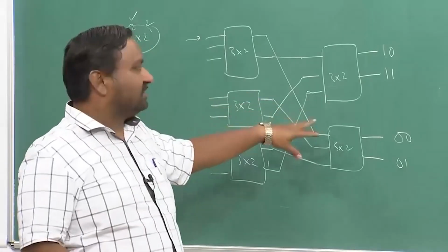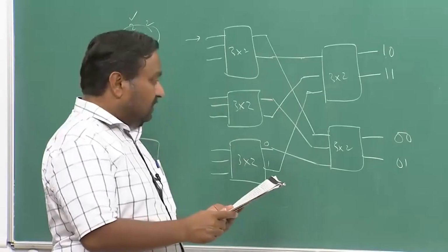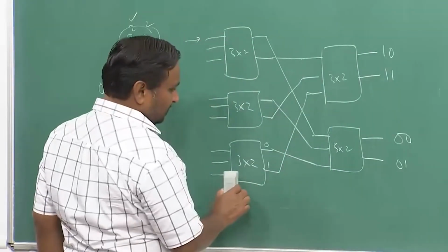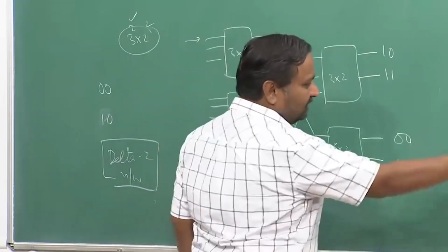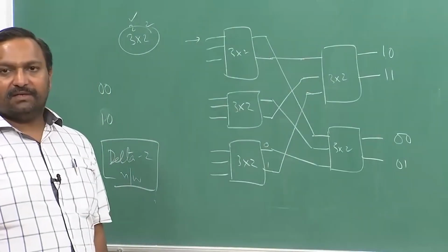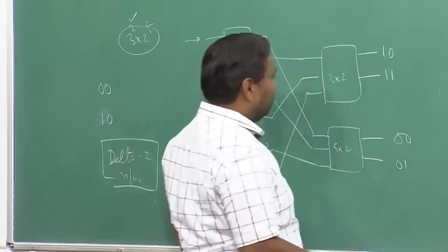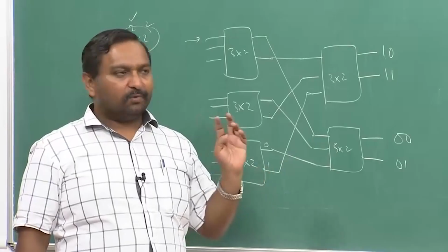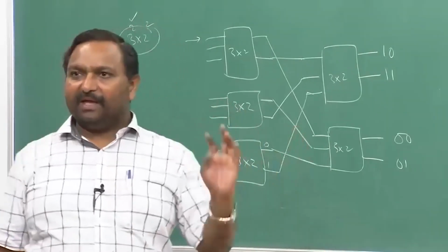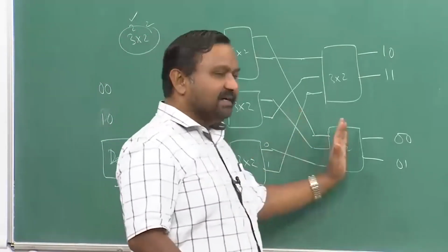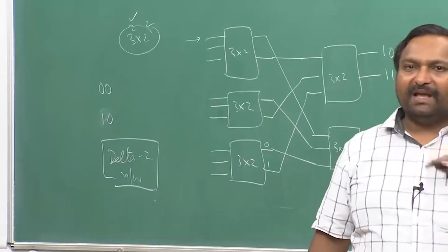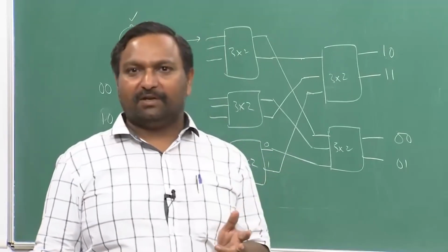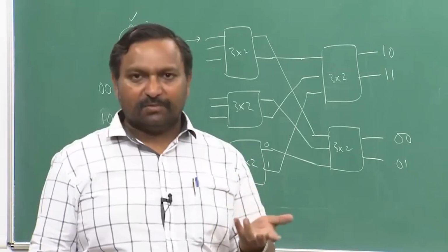But this is an asymmetric network, but it is a delta network. So, we can actually have many kinds of combinations, interconnections which can be done, but now the problem is I need something for a symmetric system so that this interconnection can be replicated very easily when you do fabrication, when there are k stages. If I am not able to repeat this particular system again and again, every time I have to make a different interconnection pattern, and while fabricating, this will become difficult. So, the question is, if I can make a switch of A by B, A by B switches, the interconnection pattern from first to second stage, second to third stage, third to fourth stage should be exactly the same. And if I can do that, I should still be able to build up a self routing network. So, is that kind of switch possible or not possible?